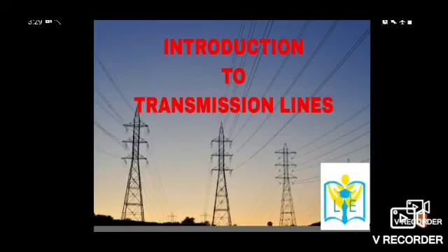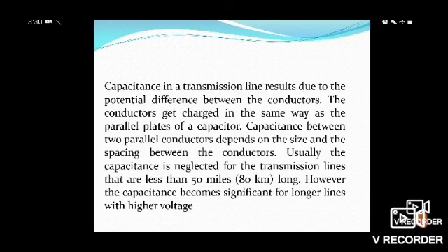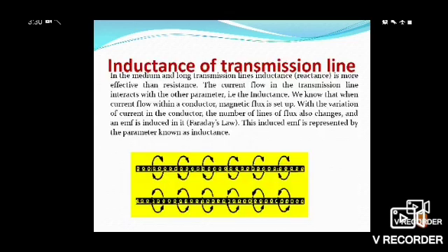What is the capacitance of a transmission line? Whenever we have some potential difference between the conductors, they are going to get a charge in the same way as the parallel plates of a capacitor. So we have a capacitance between the two parallel conductors, which depends upon the size and spacing between the conductors, and that is the capacitance.